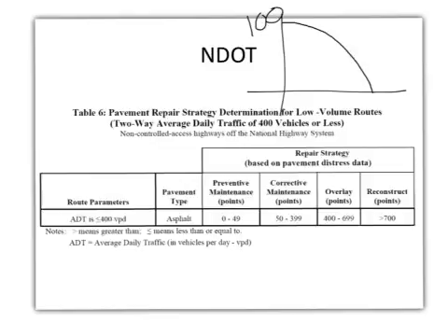So it keeps accumulating. Let's say I go to the field and I see some fatigue and some rutting and a couple of patches. Every one of those is going to have a certain amount of deduct points to accumulate, and therefore their system goes in the other direction. If the pavement is really good, then there are no points accumulated, and therefore this point here is going to trigger a preventive maintenance.